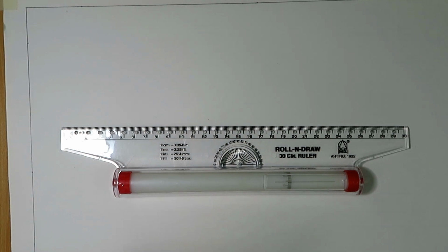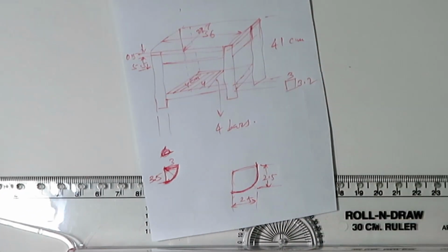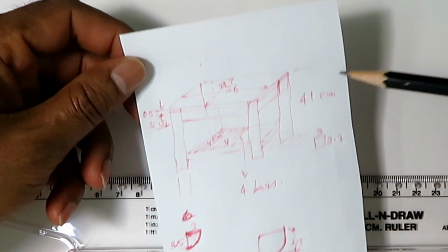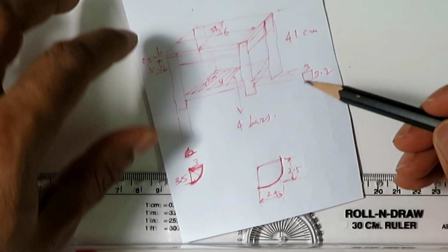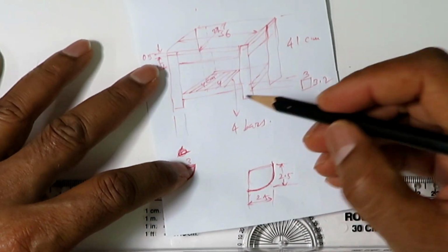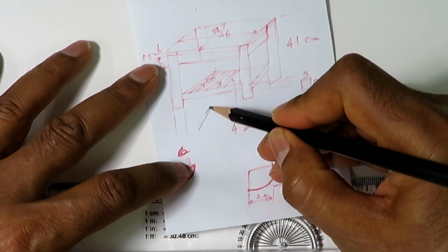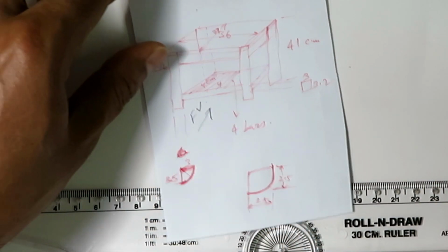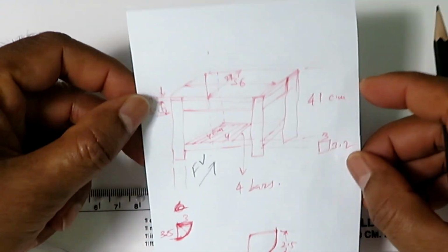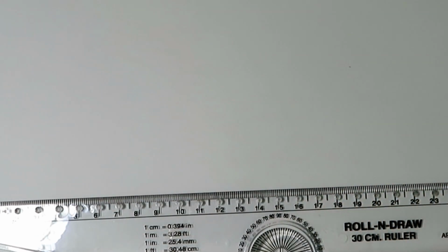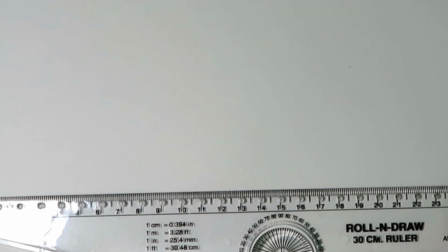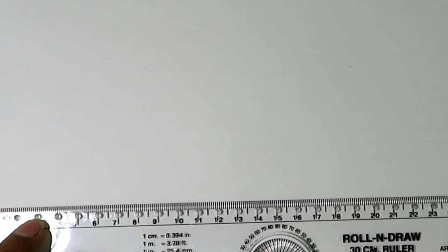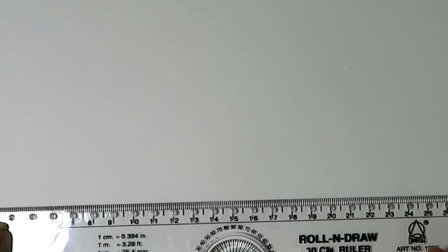So this is the drawing sheet, and I have done a small rough calculation. You should always do a rough calculation so that you can draw freely without any mistake. So here all the dimensions of that stool I have written down. These are all actual dimensions, and this will be the front view that I will draw. But as I told you, I will use 1:5 scale, so all the dimensions will be divided by 5, and that's the dimension we will use here.